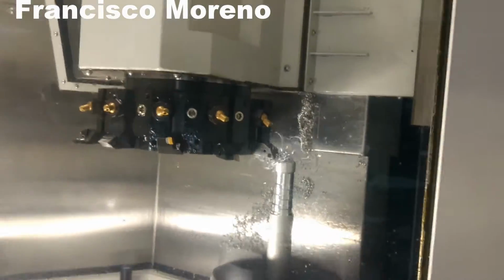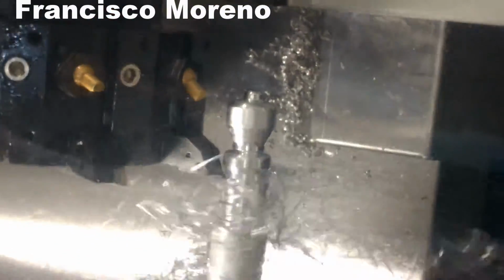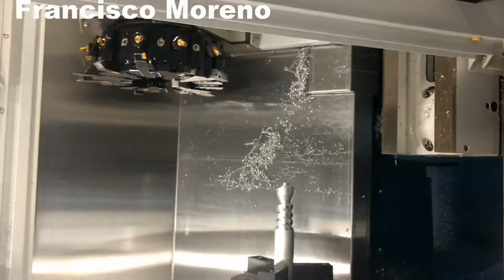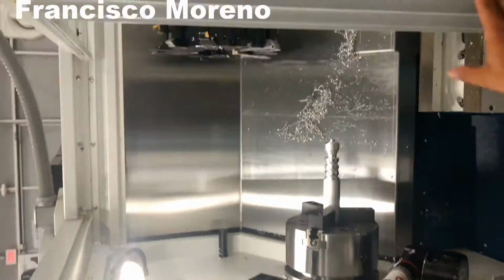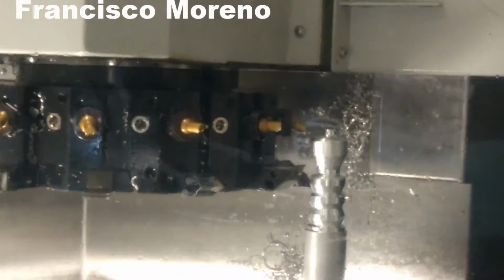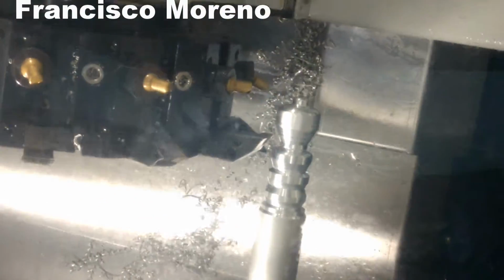It only takes one pass to do the facing, and after that the roughing process begins. The piece is a bit too long, so there were some unwanted vibrations. Roughing is used to remove material approximately towards the final shape. We can see on the tip of the piece how the vibration gave it a rough surface.